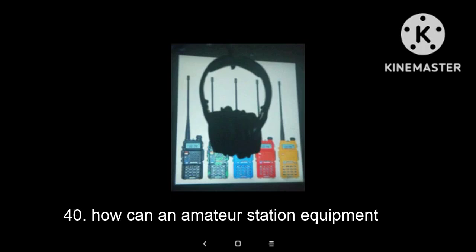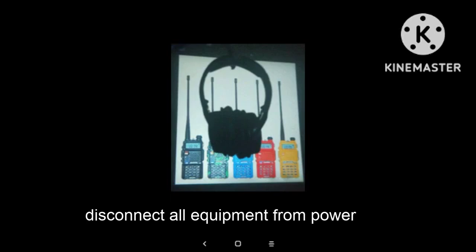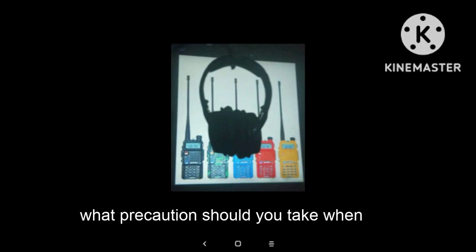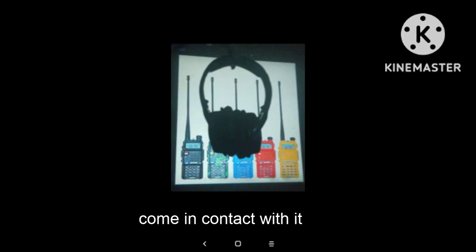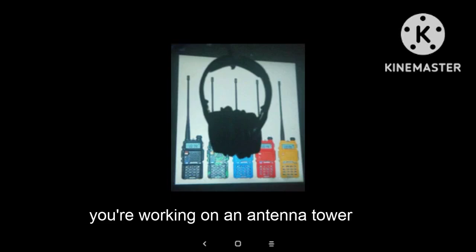40. How can an amateur station equipment best be protected from lightning damage? Disconnect all equipment from power lines and antenna cables. 41. What precautions should you take when installing a ground-mounted antenna? It should be installed so no one can come in contact with it. Number 42. Why should you wear a safety belt if you are working on an antenna tower? To prevent you from accidentally falling.